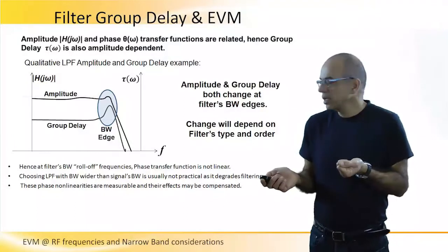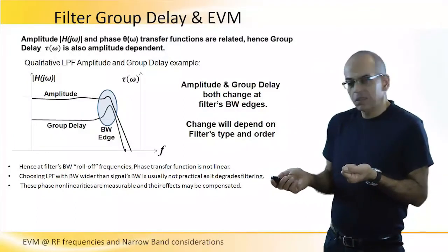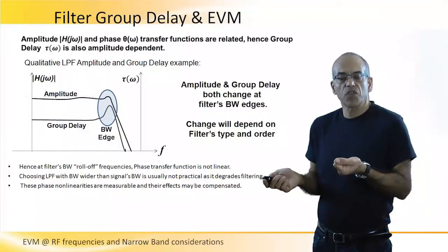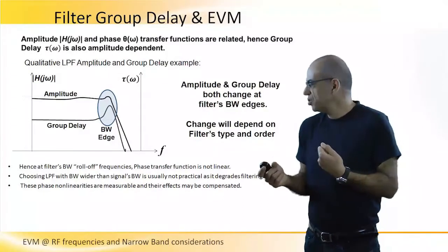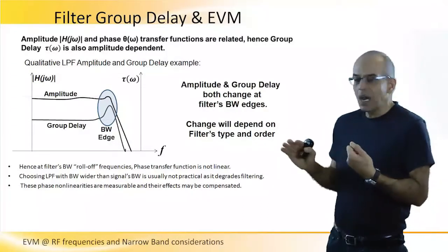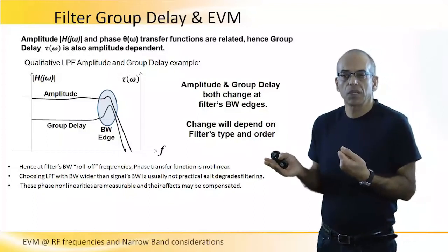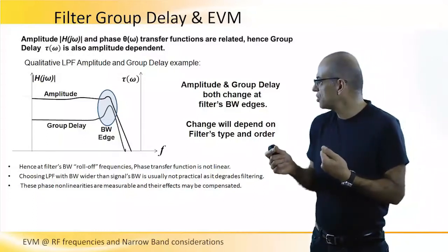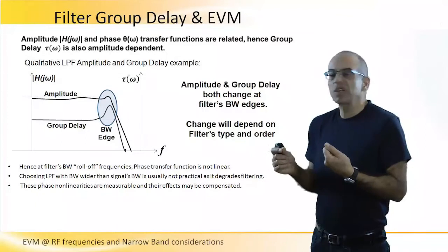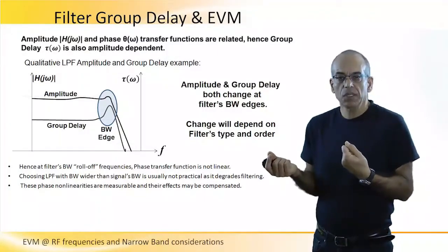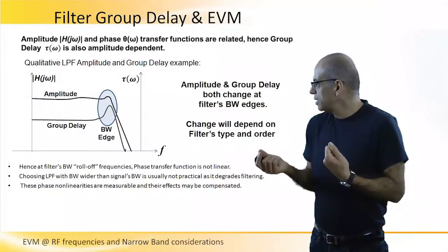However, amplitude and phase transfer functions are related, and so at the band edge where the amplitude is changing in all filters, also the group delay is changing, and it is not constant anymore.